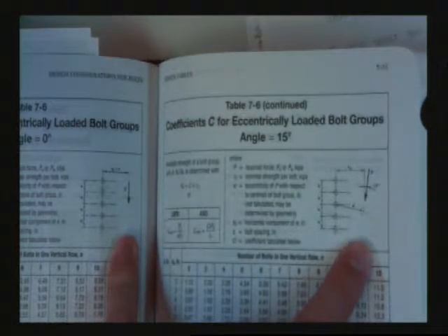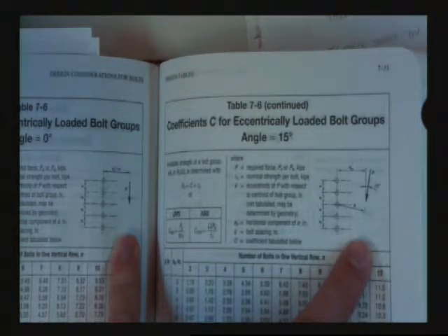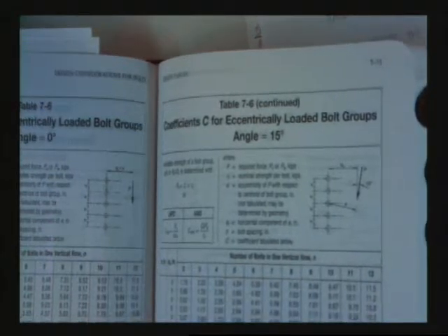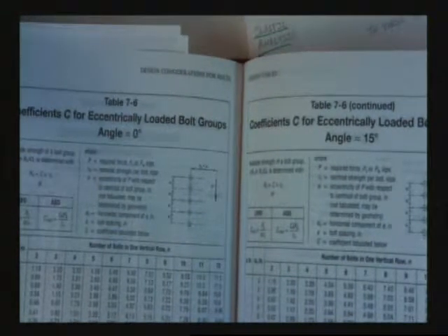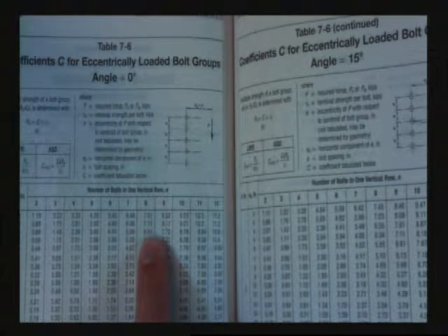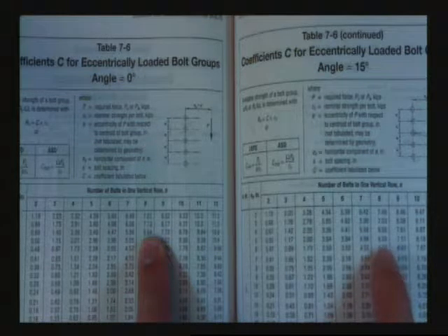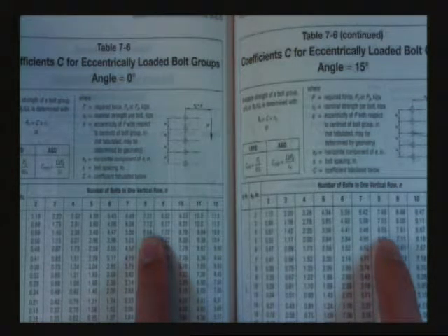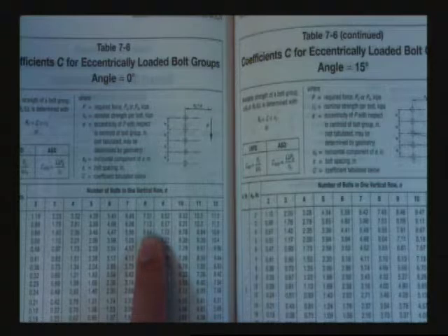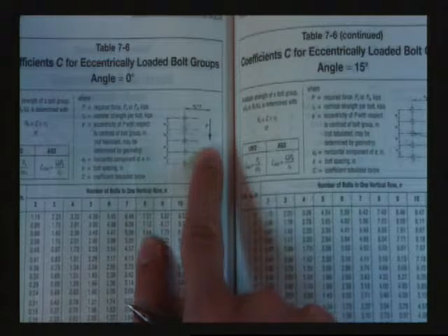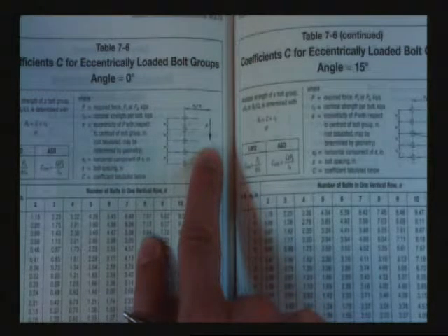Now, you can linearly interpolate between any one of these values. The only thing you cannot interpolate between is your angles. Let's say you have a load that's at a 7-degree angle from the horizontal. You cannot take a linear interpolation, basically solve for what the value is here, solve for what the value is here, and interpolate in between them. Absolutely not conservative. Not allowed. So what do you do instead? Use the one that's most conservative, right? Which I think almost always corresponds with the lower angle. Should always be the lower angle.